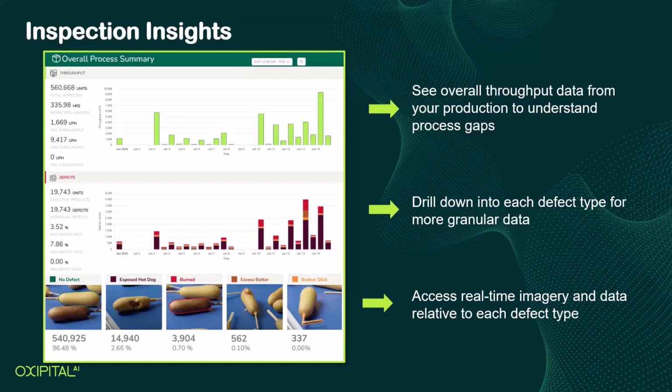If you have ears of corn that need to end up in a tray, but they're too long, then you're going to have problems when those trays head to the overwrap machine. At the same time, if you're seeing ears of corn that are cut too short, then you know an operator is likely loading a cob saw incorrectly upstream, which is decreasing your yield.